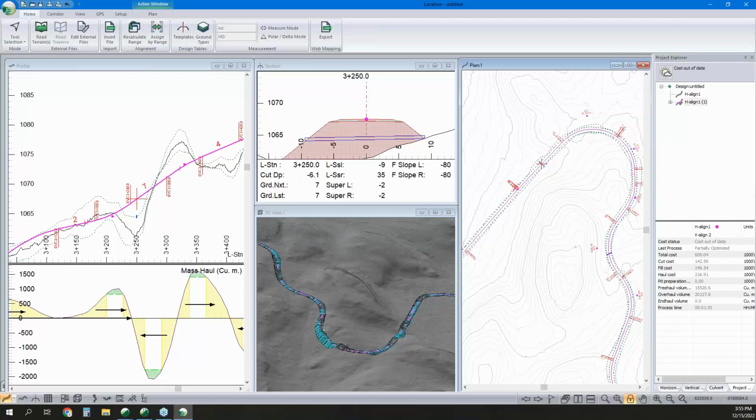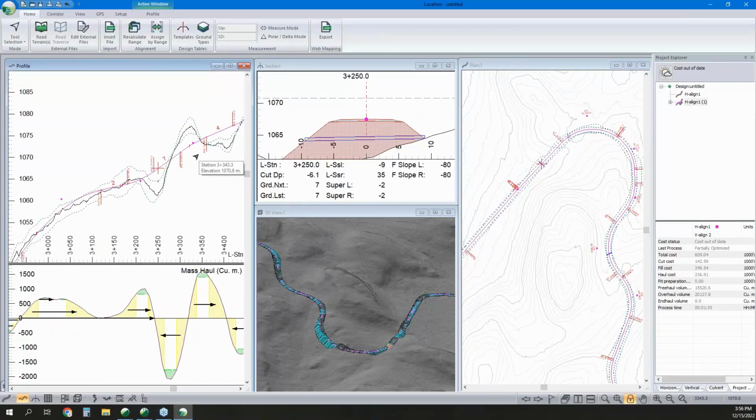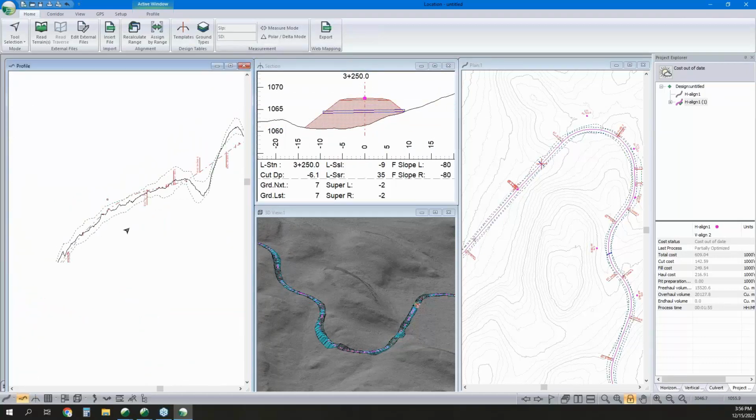The first question is, how does the program deal with changes to the layout or end haul locations after that preliminary design? So you're not stuck with it. You can move this around however you like. Now, end haul in that context, I assume it's referring to your full bench constraint. If that full bench constraint's a product of where the position of your road is, so let's go somewhere.